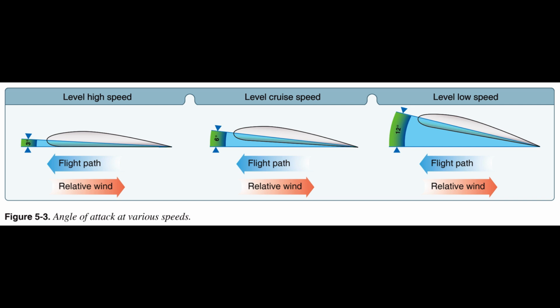Straight and level flight in the slow speed regime provides some interesting conditions relative to the equilibrium of forces. With the aircraft in a nose-high attitude, there is a vertical component of thrust that helps support it. For one thing, wing loading tends to be less than would be expected. In level flight, when thrust is increased, the aircraft speeds up and the lift increases. The aircraft will start to climb unless the AOA is decreased just enough to maintain the relationship between lift and weight. The timing of this decrease in AOA needs to be coordinated with the increase in thrust and airspeed.